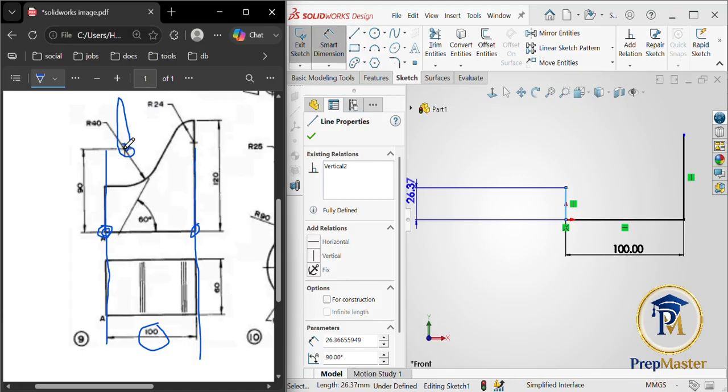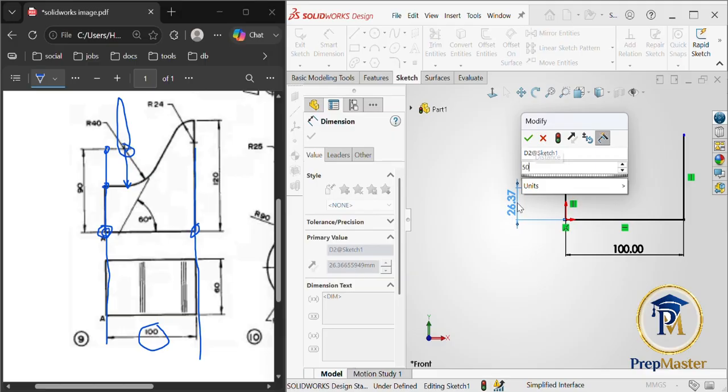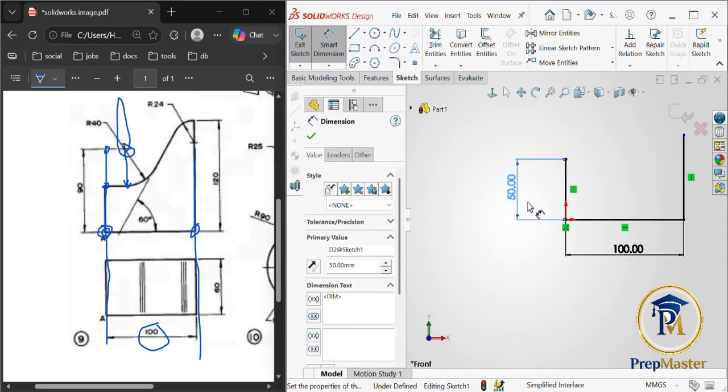If you bring the radius down and set it at 90 degrees to this horizontal surface, it will still give us the same radius again. So that will be 40, meaning the distance from here to this part of the surface is 40. So 90 minus 40 is what? 50. That means the distance here is 50. So click on it, type 50 and press enter.